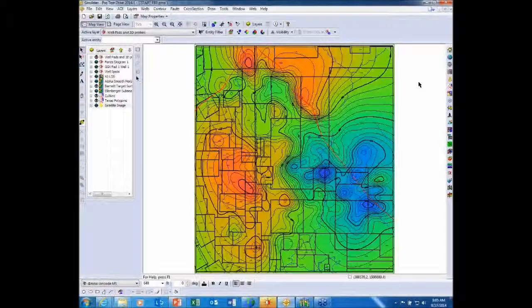You're viewing currently GeoAtlas. On GeoAtlas, I'm showing a number of layers, including 4 different well-based layers, 1 cross-section line of section, 3 isomap layers, 2 cultural layers, and a satellite image. The 3 isomap layers were built from an analysis of the reservoir properties in PRISM and further refine the geometries by using depth-converted seismic horizons from SeisVision, and all converted to depth to display here. Currently, I'm only showing the Barnett target surface. This is the surface that we will be planning the wells along.